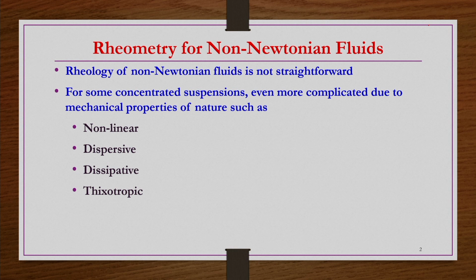Now, before going into the details, one thing I wanted to mention. Most of the non-Newtonian fluids are not single phase materials. The majority of non-Newtonian fluids are multi-phase particulate systems like emulsions, suspensions, soups, etc. These are materials where there are some constituents within the solution that we have taken.